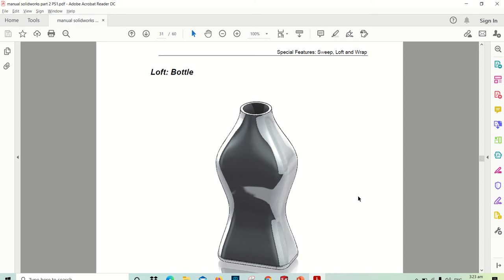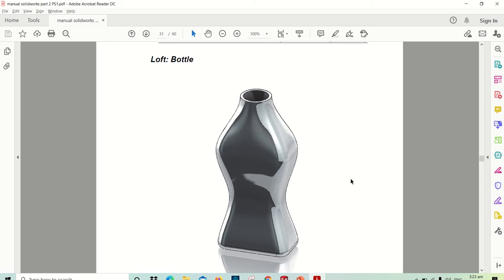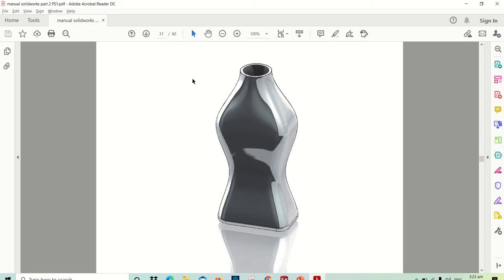In this training video, we will now learn how to model the CAD using a loft feature. We could not model this one using the typical revolve or extrude command, because it has a different outer surface. This is not the common extrude or revolve feature, so it would be very hard to do with extrude, or it would make us work more or use extra commands just to create this profile rather than using the loft command.